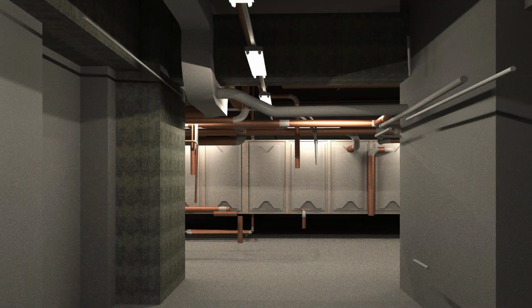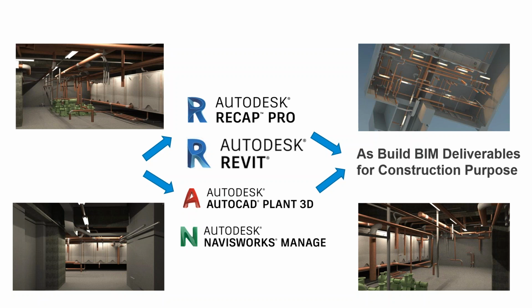Okay, a few more snapshots. So how did I go through this whole process? As I mentioned, I talked about two tools. I talked about taking the scanned images coming from your laser scanning equipment like Topcon, Faro, etc., bringing them into tools like ReCap Pro, modifying and cleaning up that information, and stitching those images, which you do inside ReCap Pro, depending upon the type of project.